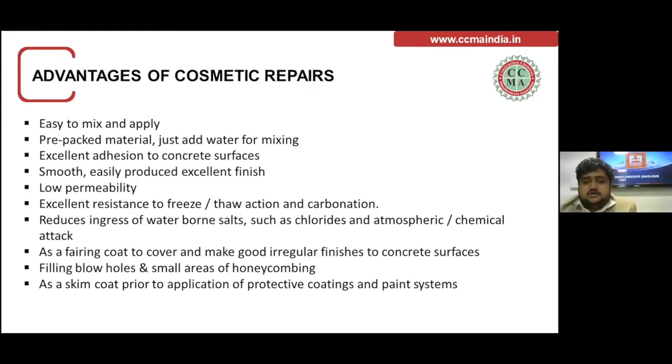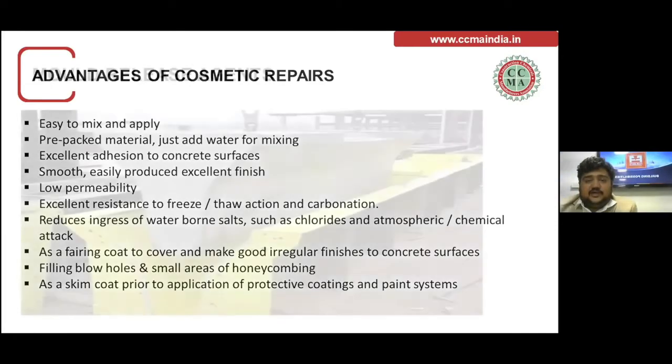So if you use a fairing coat, which can fill up small micro bubbles and give a single color, it gives a fair-faced concrete as a skim coat prior to application of protective coating and painting systems. So this also helps wherever you are applying or going to apply a protective coat or a paint. This will help for the adhesion to the concrete. It will enhance the bond, and the pinholes will not be there and the finish will be better. So that is the main use of cosmetic repair.